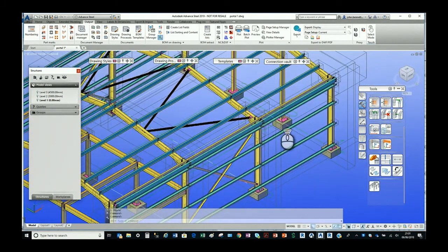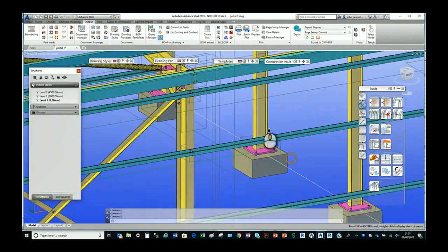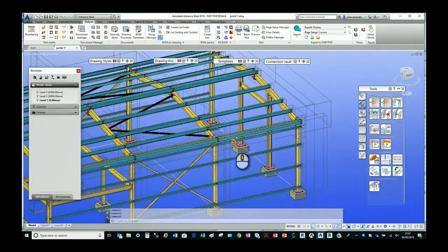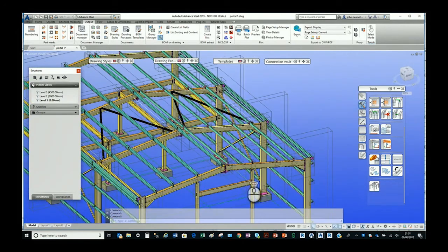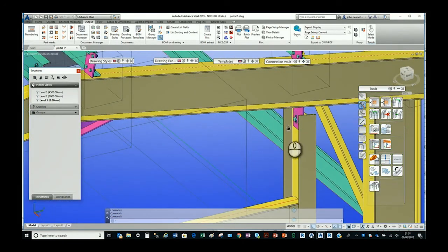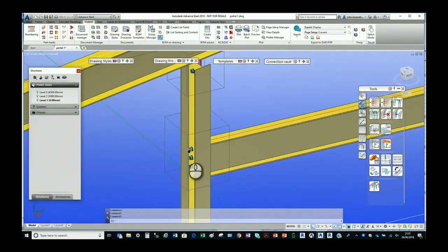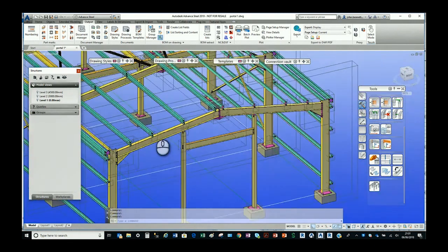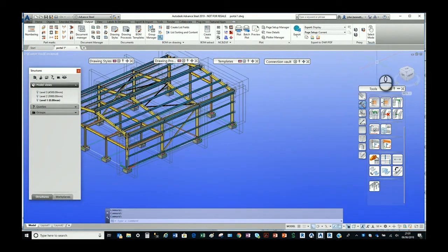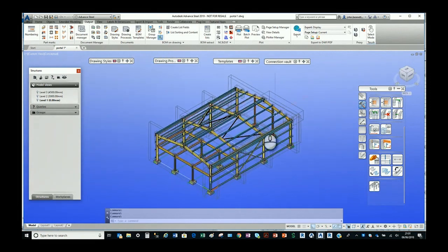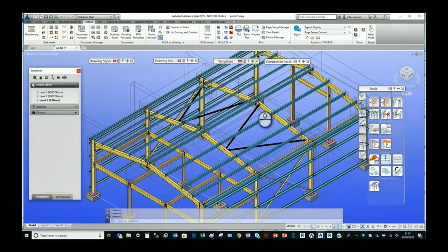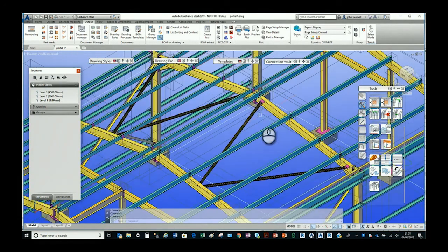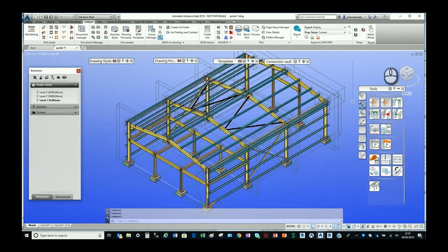But I put standard base plate connections on. All these are standard joints that are available inside Advanced Steel, and I just wanted to see whether they would come across into Revit, or at least whether I would get the plate and the nut and the bolt with it, or the cleat. And I put a little test level in. I put that beam that's in there, the header beam of the door, in at level 3 inside Advanced Steel. So I've got levels in my Project Explorer on the left hand side of the screen. There are slightly different brace tube based connections in the roof, just to see if that would work from the normal ones we would use in the UK.